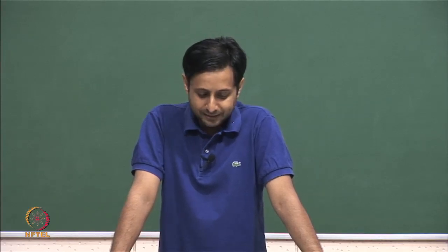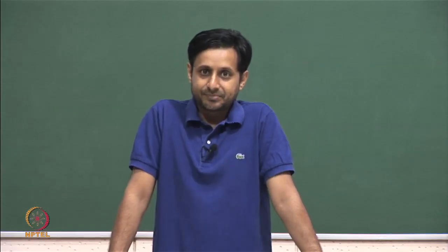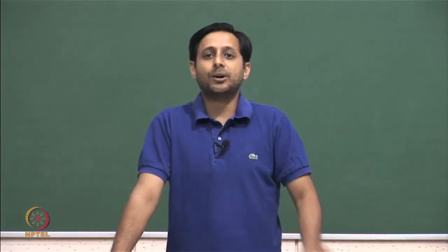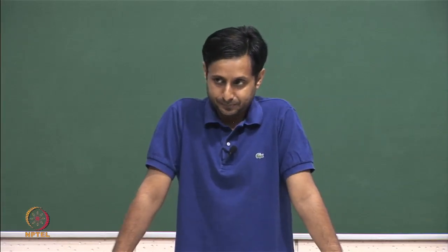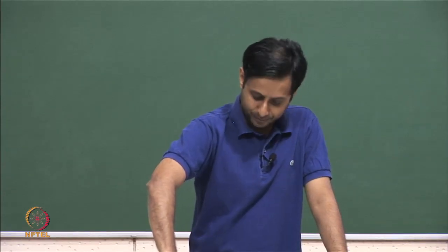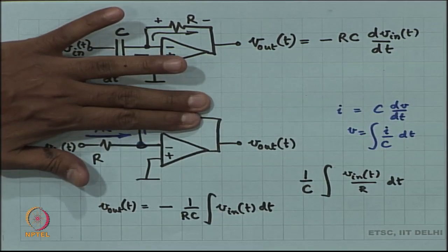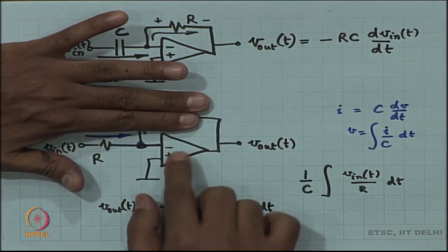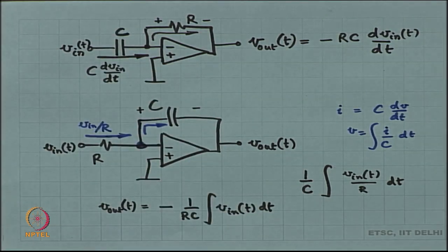There is one more way of seeing this. If you look at this particular circuit, then at DC, when you try to work out the DC operating point, at DC this capacitor is an open circuit, okay, it does not exist at DC, which means that there is no feedback around the op amp.